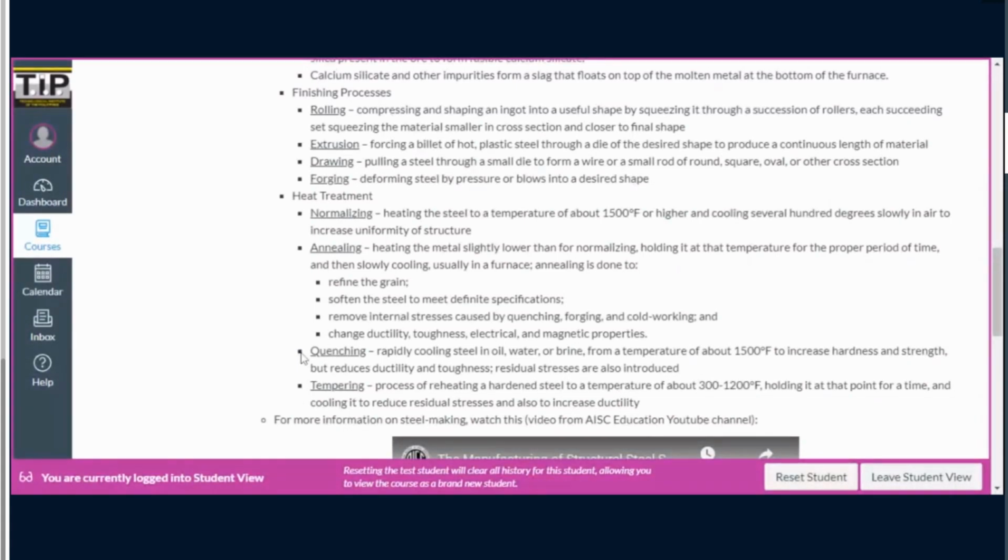So that's what we avoid in reinforced concrete. You don't want your steel to be too strong because otherwise it will not reach its yield strength. So meaning the failure will be compression controlled. So that's the issue with quenching and tempering for rebars. But for structural steel, this one is pretty much normal.